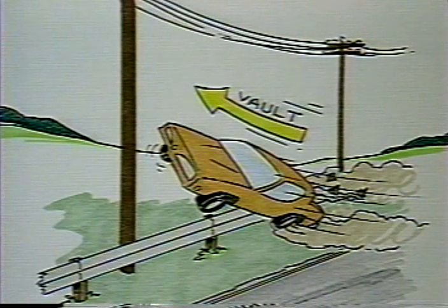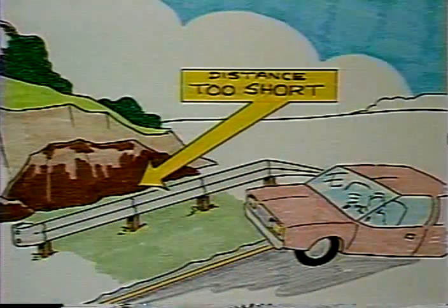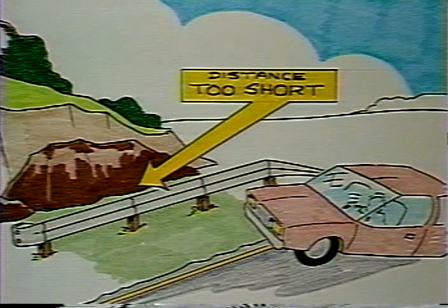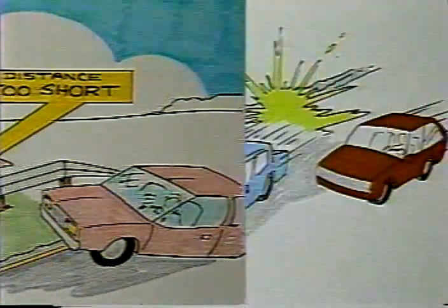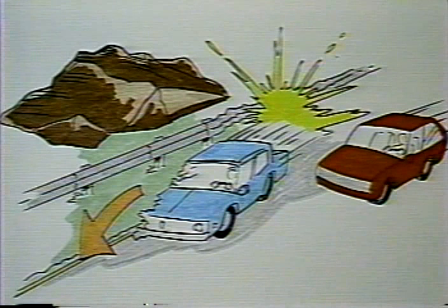If vaulting occurs, the system has failed. If the system fails, death or injury will likely follow. The distance from the barrier to the hazard is important. If the barrier deflects inward all the way to the hazard, it obviously will not provide much protection for the motorist. The distance from the barrier to the outside lane of traffic is also important.